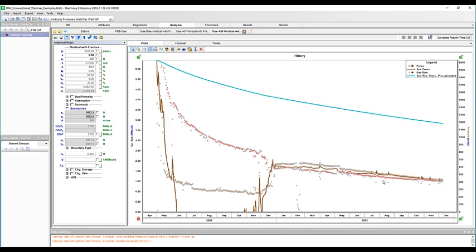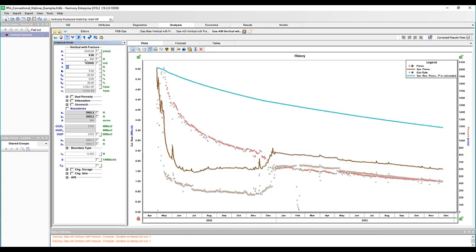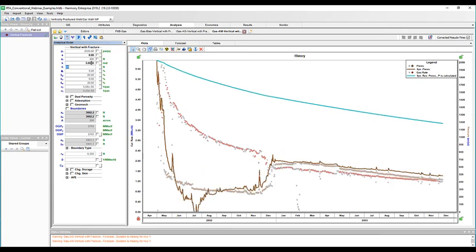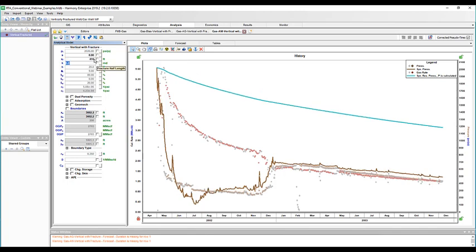So we actually need to start tweaking our inputs. And usually, if we start by adjusting the permeability and the fracture half lengths, this will sometimes give us a little bit of a better match. So let's try doing this. Now you can see through trial and error how tweaking these inputs will make a difference to the history match. I've increased it slightly and you can see how it still hasn't matched. I can then decrease it slightly and see that we're getting a little bit of a better match. I can also play with the fracture half length and see how this will actually change my match.